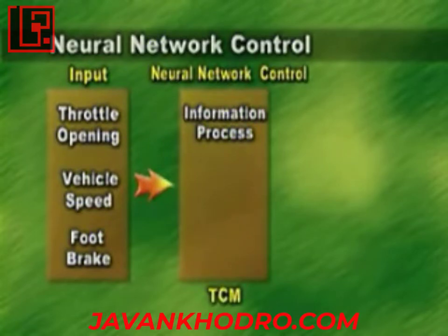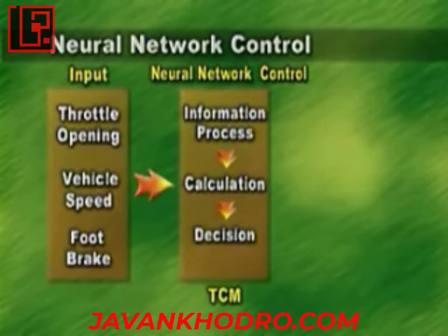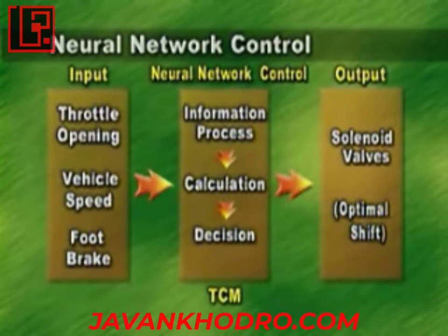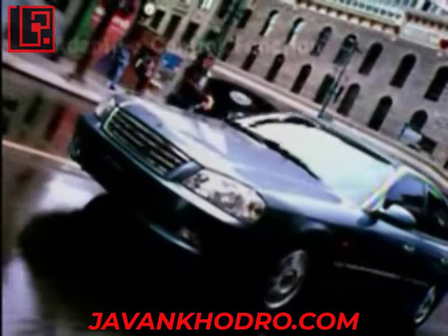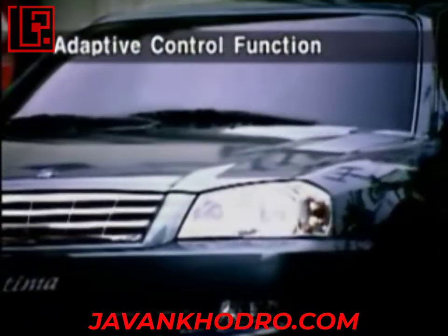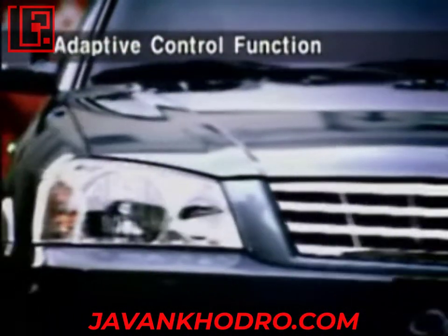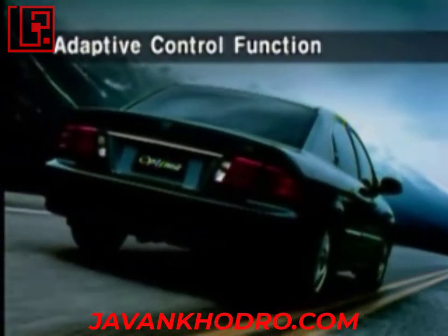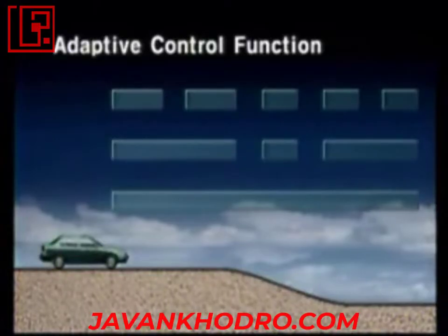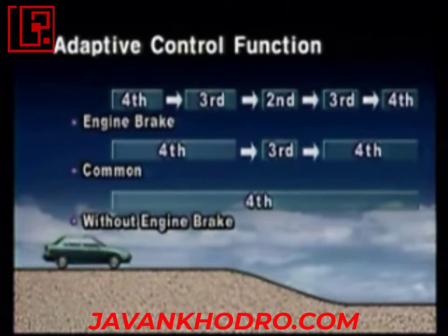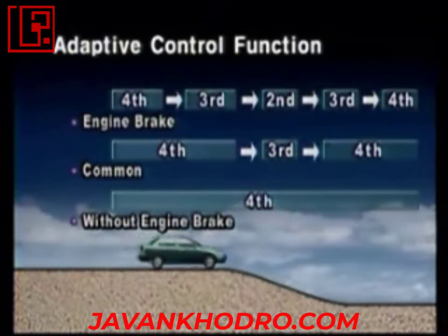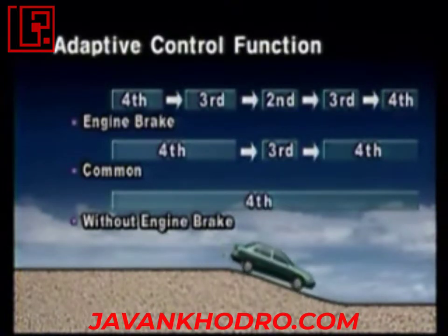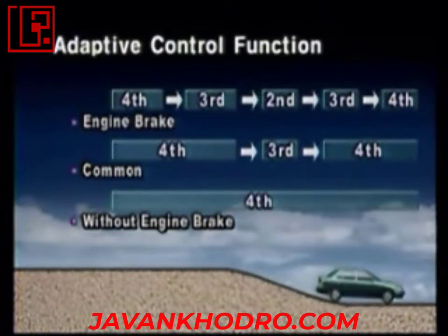Downhill downshift function performs a downshift to operate an engine brake according to the data, such as the slope of the road, braking force, and vehicle speed through a neural network. Downhill downshift adaptive control function means learning the operation condition by reading if the engine brake amount is low or excessive from the throttle control and the braking. So, it enhances the driver-friendly downshift on the downhill.